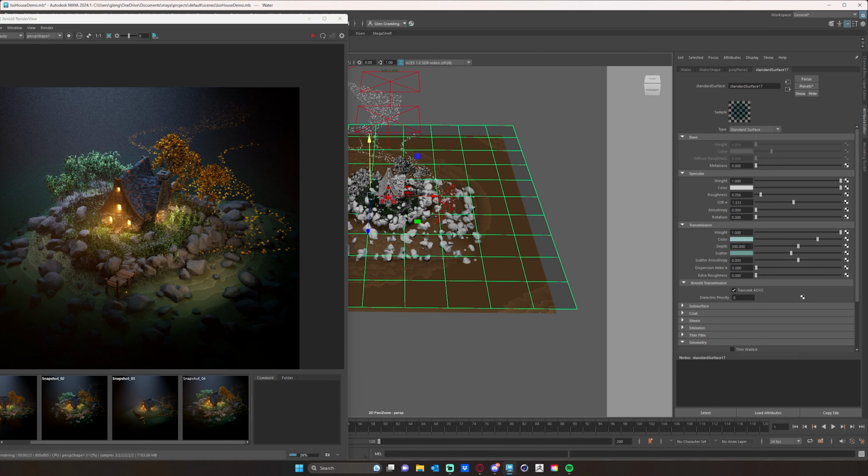And now this depth, this isn't like how deep the water is. This is how deep the light penetrates into the water. So the higher value this depth level is, the more transparent your water is basically going to be. This was originally at 100 and I cranked it up to 300. I might put it back down to 200 just for now.